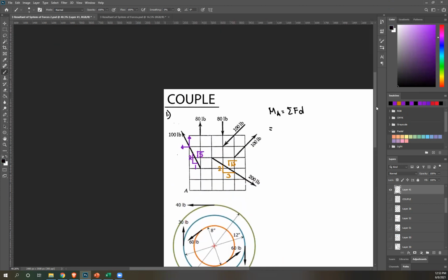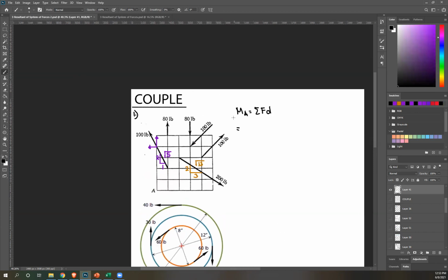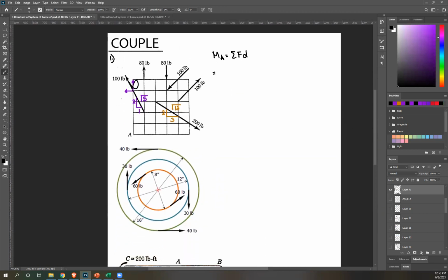Now, before, what we did was we solved for the horizontal and vertical components separately, but now we can just include it all in our equation. You may do this if you're used to getting the components already. So once again, y component, ignoring that, we're left with the x component. Rotate that about A. That's counterclockwise, therefore negative. Get the horizontal component, so that's just copying the force multiplied by the horizontal side, so that's 1 over hypotenuse, square root of 5. That's the horizontal component.